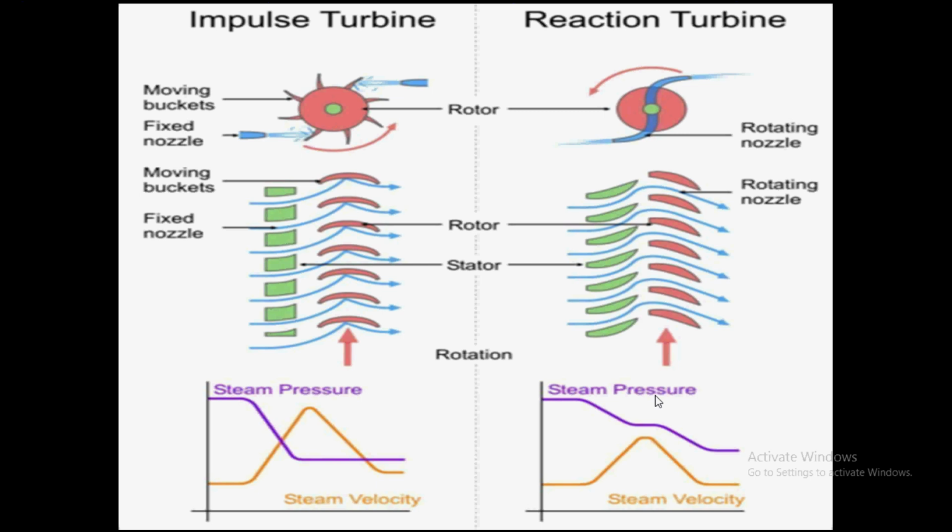So next one is packing. Packing is provided for preventing leakage across the annular space between the diaphragm and shaft, and casing and shaft. Packing is provided in the form of carbon rings. Carbon rings present an effective seal against shaft leakage in small turbines and are extensively used with water seals for preventing shaft leakage in larger turbines. A carbon ring consists of a ring of carbon, rectangular in cross section, and usually divided into 4 segments. Rings fit into a recess in the casing and are kept tight against the shaft by means of a garter spring.